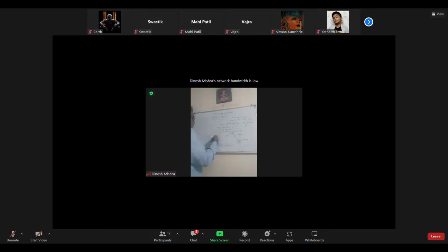When the spindle moves, the gravity weight is also lifted, and it controls the movement of the spindle. Understand? So it will control the movement; the gravitational force is opposite to the deflecting force, and here the spring is opposite to the deflecting force. So these are the two types of controlling system: the gravity controlling system and the spring control system.